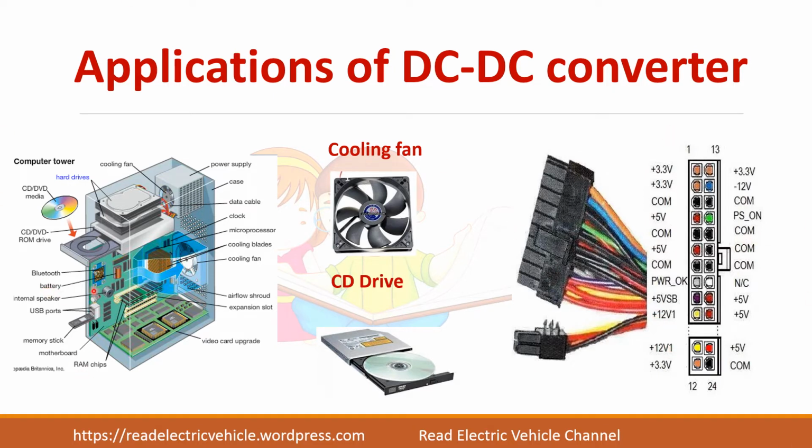We will give an AC supply to the CPU which has an inbuilt rectifier which converts to DC. That DC input will be given to this DC-DC converter. From that you can obtain the required voltage.